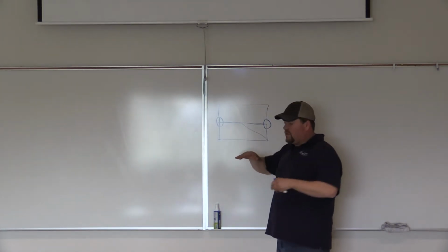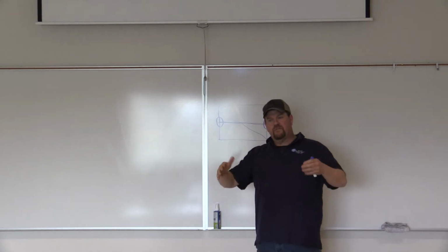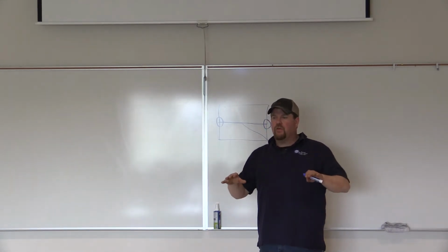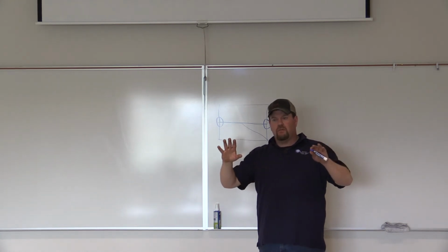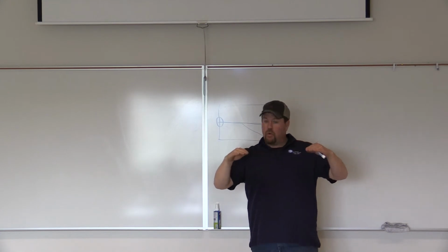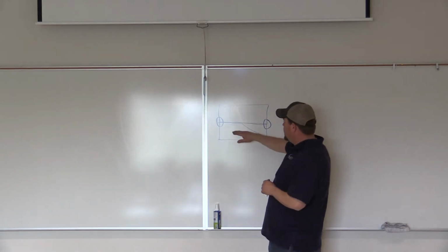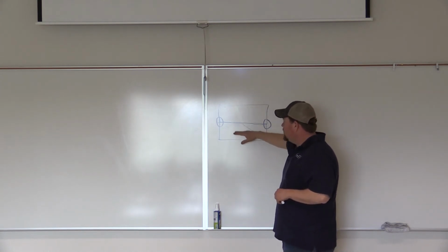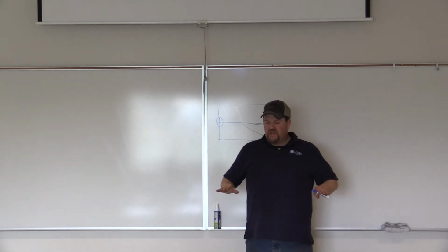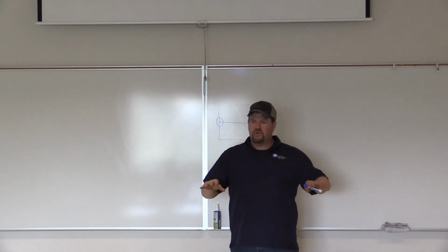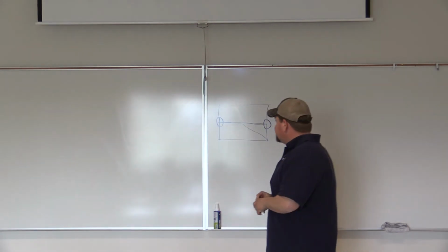Where we would see this would be on, for example, a snowplow. A snowplow is going to run up against the road. Well, you don't want the blade to hit exactly on the road, otherwise it just tears up the asphalt, right? So you want it to set just a little bit above. So you put basically a road bumper underneath of it, and your road bumper can be something just like this. It's built with a spring tension here, it comes down, and you're able to see that rubbing across the bottom. It's got a plate there of a mild surface, and only two things are working along as you're going across the road, all right?